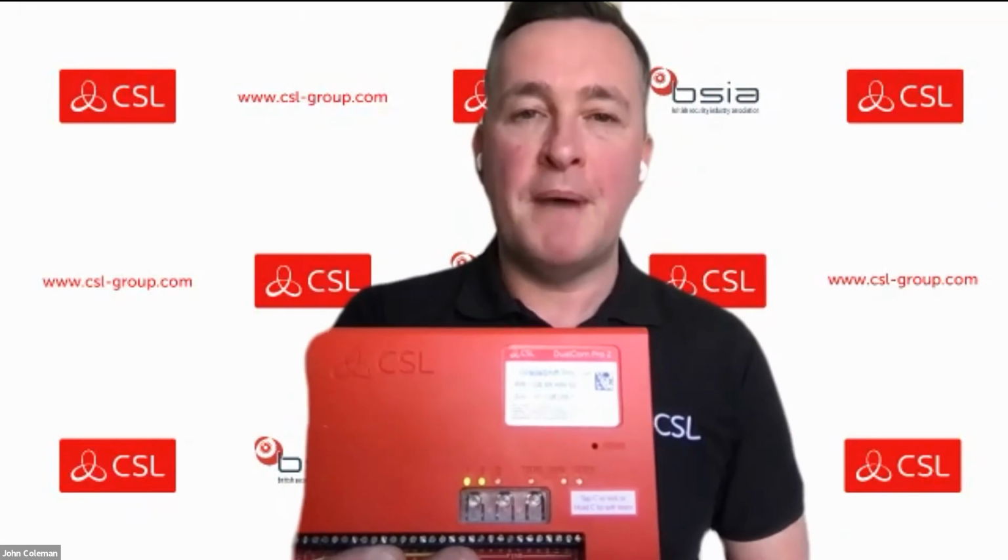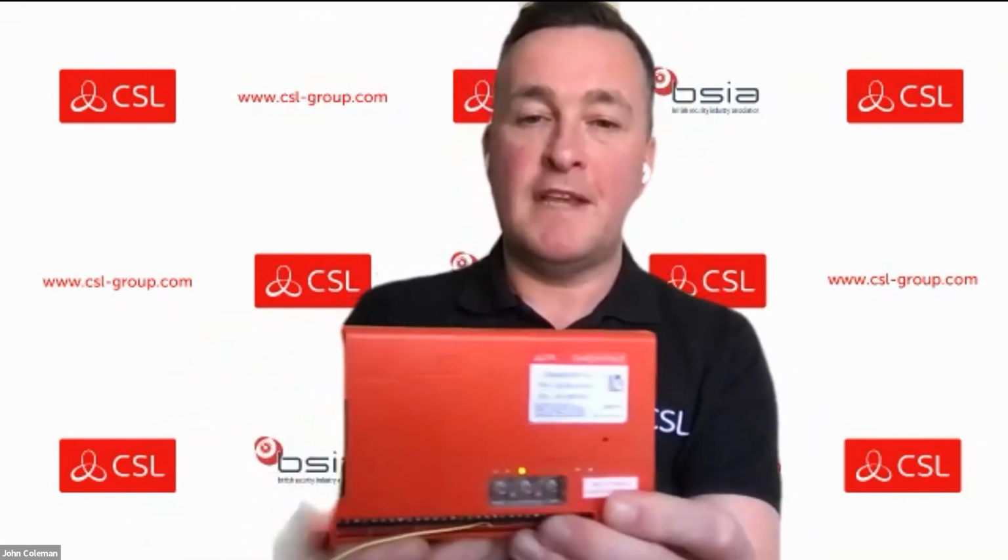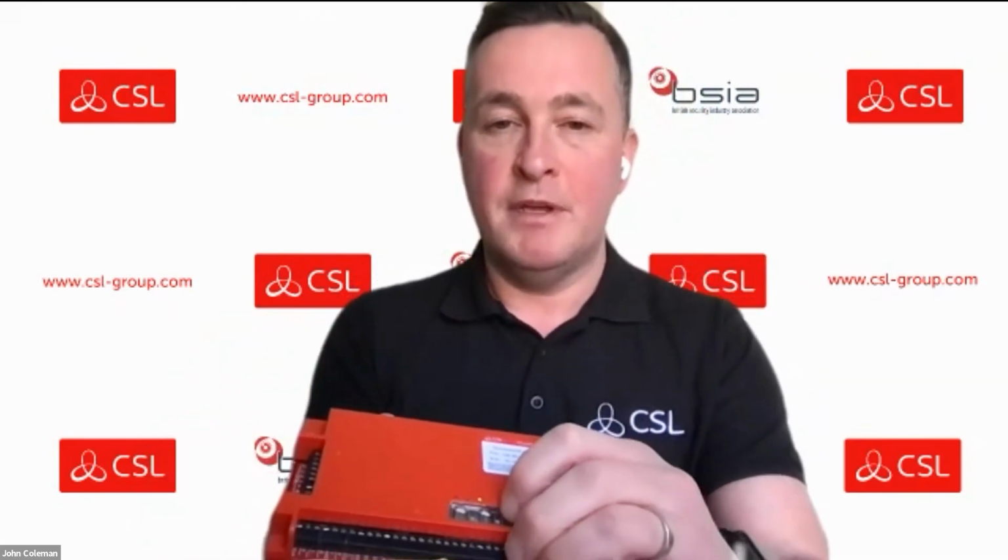I also mentioned before about self-learn and sending test calls. For self-learn, we press and hold button C for, as I said, roughly about 5 seconds. And we've now done a self-learn on the device. Then to trigger the test calls, as I mentioned before, you would just tap button C, and that will send test calls through to the monitoring station.